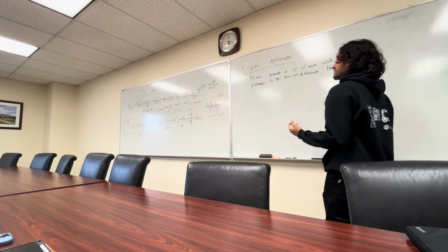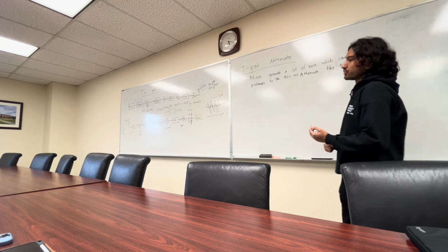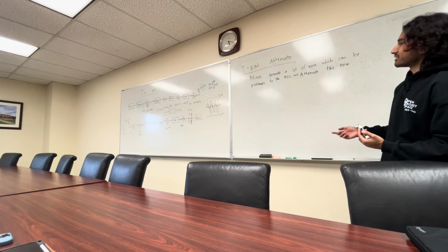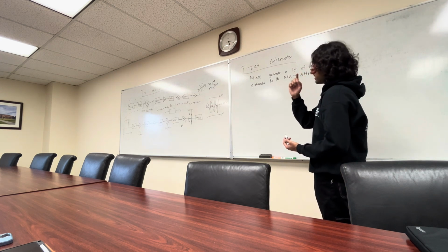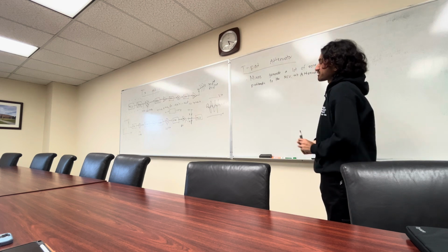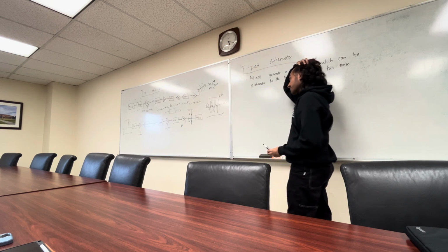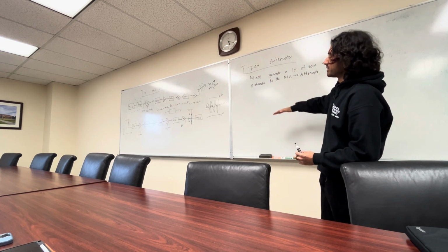And qualitatively, we can reason that mixers produce a lot more noise than standard blocks. I'm not going to go into the math there, but if you'd like, you can ask me later and I can show you that little derivation. But mixers produce a lot more noise than other blocks. Part of the reason we'll talk about low noise amplifiers later on the receiver is to make sure we set a good noise floor.